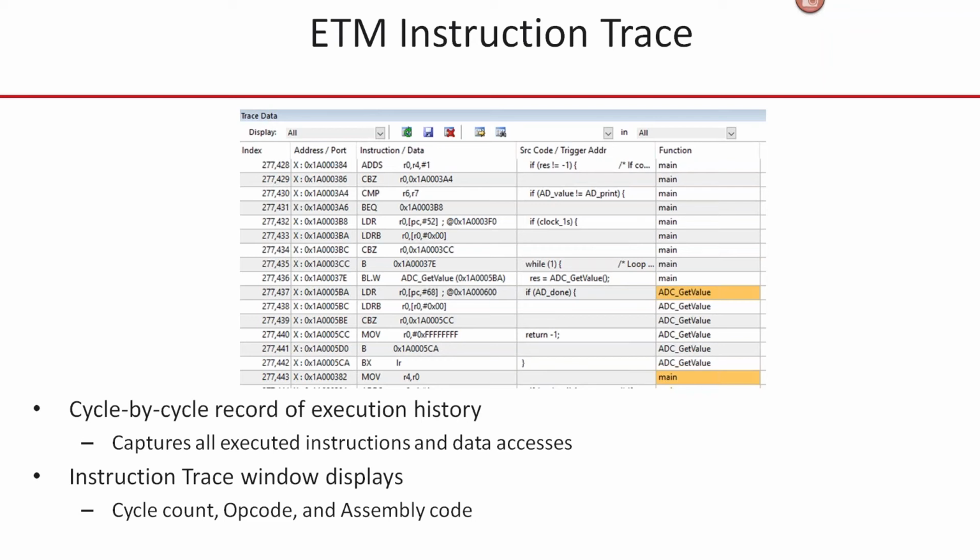All of the trace information is streamed directly from the microcontroller to your hard disk. So in effect, you have pretty much a trace buffer that's only limited by the size of your hard disk. So you can log massive amounts of information. This is very good for code coverage, performance analysis and other processes that you need to validate the tool.